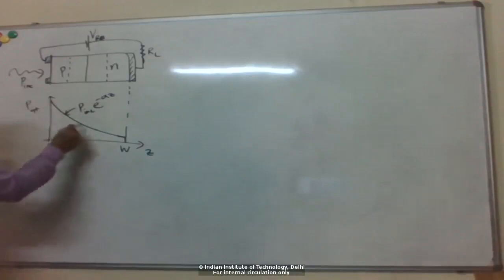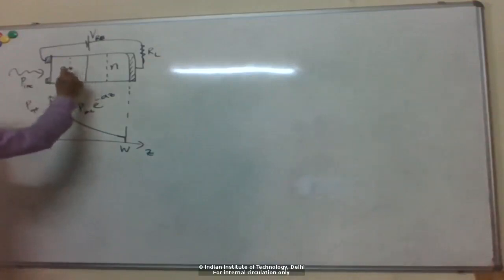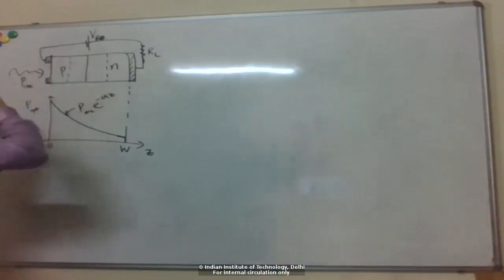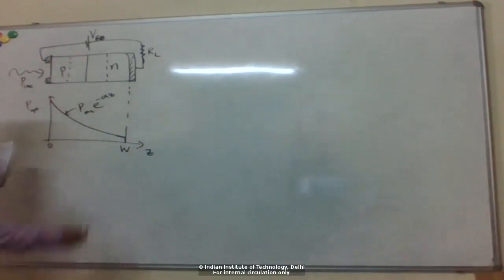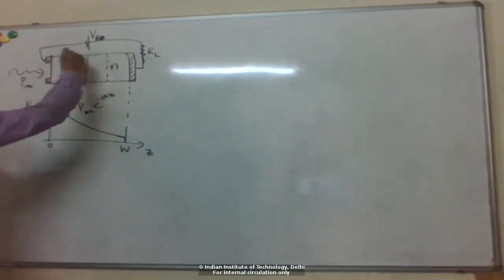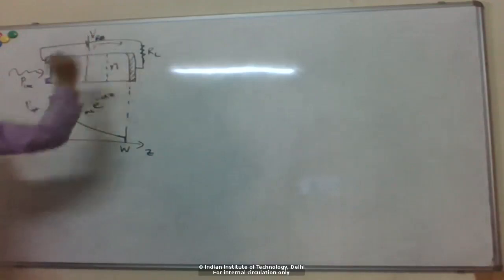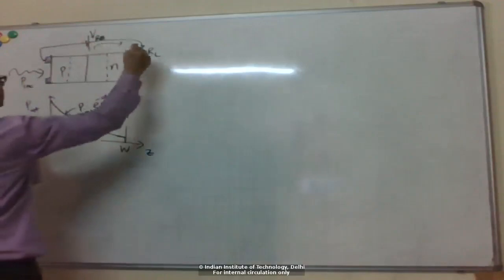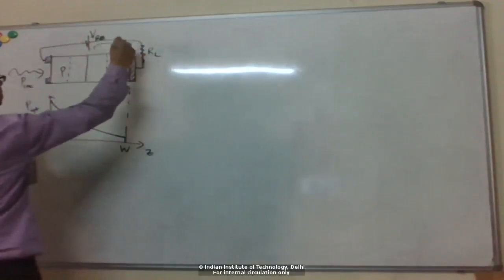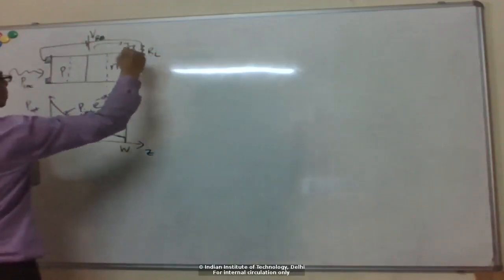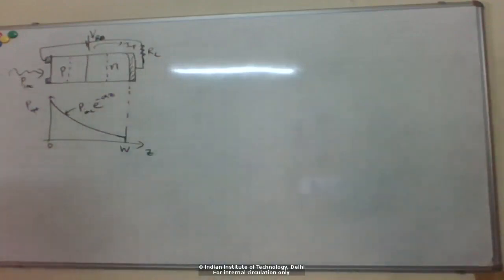Okay, so basically because of this light absorption, carriers are generated here, right? So electrons get excited to the conduction band, so you have electrons flowing in the conduction band and correspondingly holes created in the valence band, and these charge carriers can now flow into the external circuit, and then you could measure, for example, the photocurrent coming out, or have a load resistance and measure the voltage across some load resistance.